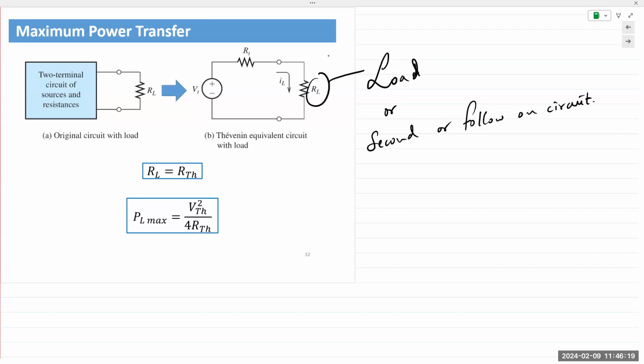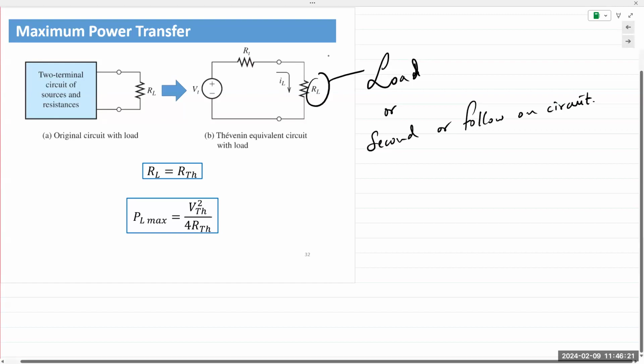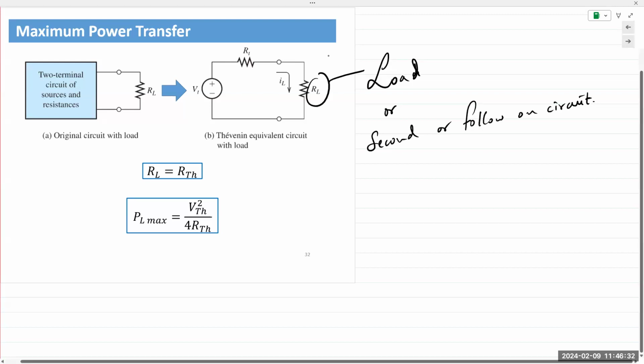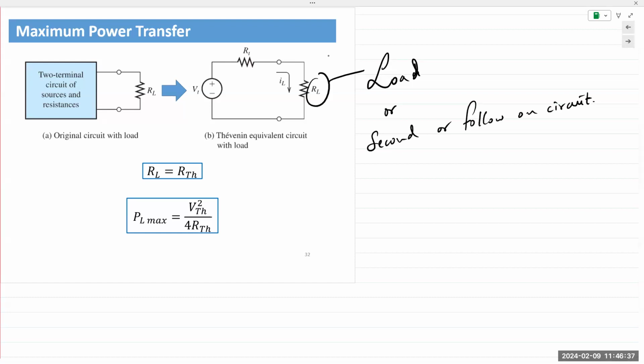That actually happened to me once at a gig. I connected the speakers, and half an hour later, I smelled burning. I realized I had looked at the specs of the speakers, and it turned out it was a 4 ohm speaker connected to an 8 ohm amplifier. So that's something you have to be very careful about. Your wired headphones are typically 32 ohms. So again, that's a real life example of where we need resistance or impedance matching.